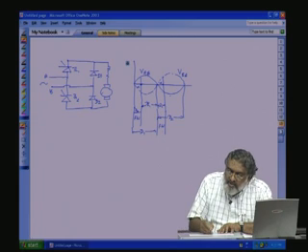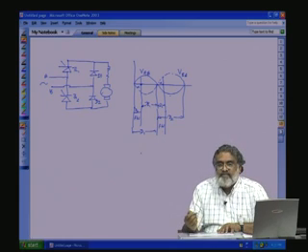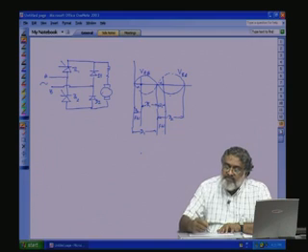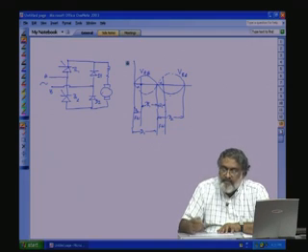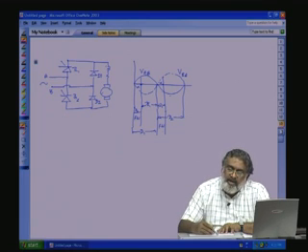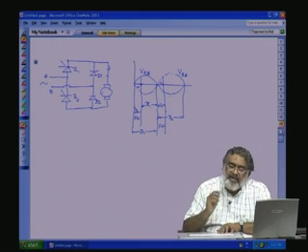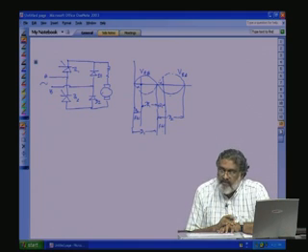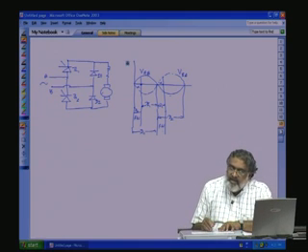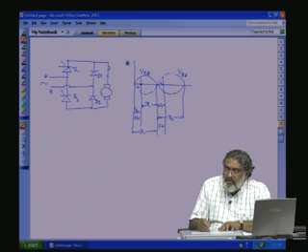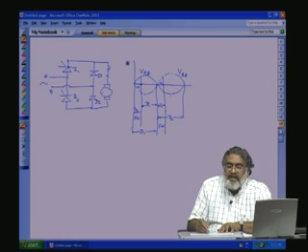is the D2 period. So when both diodes are conducting, that is whenever the VAB becomes negative, anything slightly negative, this load voltage becomes negative, it will try to freewheel through this way. The moment it freewheels, this load inductance will forward bias D1 and D2, and D1, D2 will conduct, and by then thyristor TH1 and TH2 will be switched off. So you have D1 conducting here, and here D2 and D1 will be conducting this period.